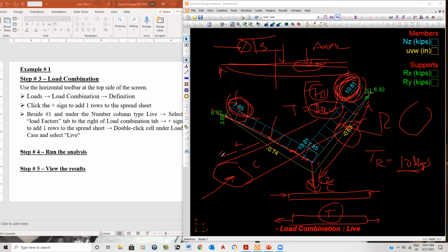And that's why it's very important to know whether it's tension or compression, because if the material is acting in compression, it has a certain resistance, and in tension, it has another resistance. They don't behave the same way, whether they're being subjected to tension or compression, okay? And steel loves to be in tension, and that's why if you can, you always subject the steel to tensile forces.